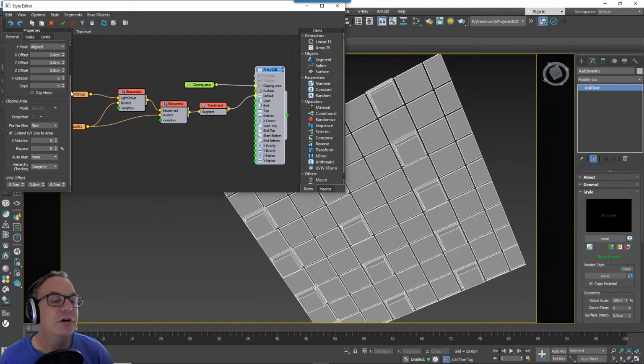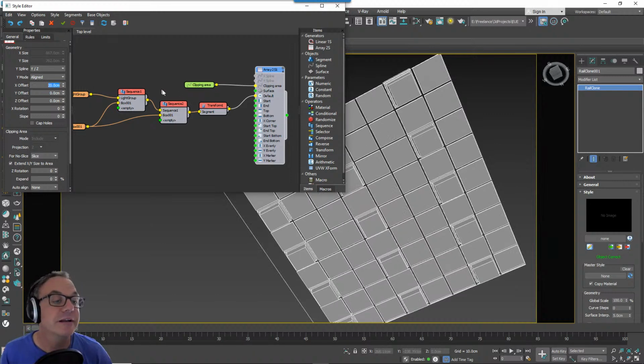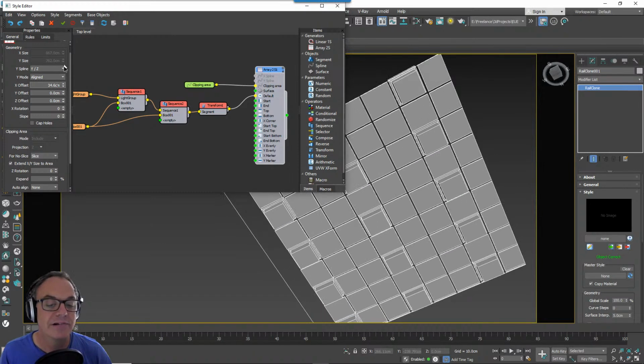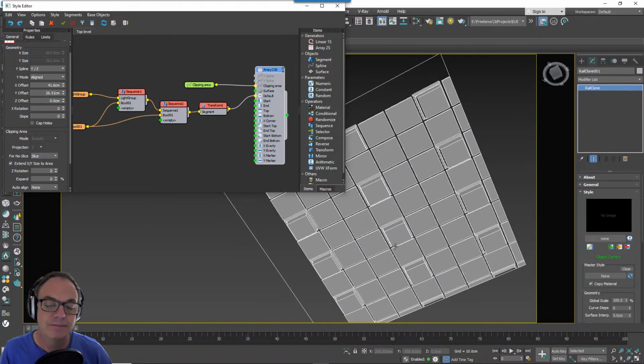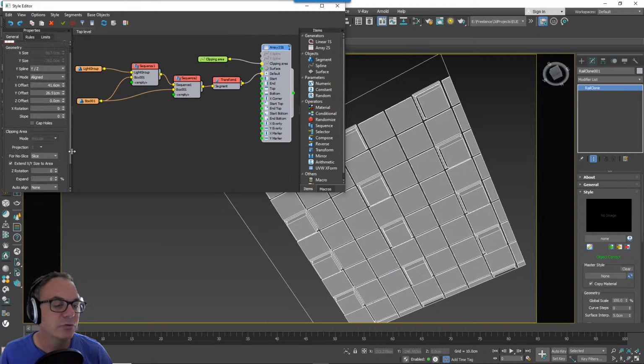If you go up a little bit here, there are X offset and Y offset modes. People have generally spotted these and they'll try to use them to slide the ceiling around. But as you can see, what happens is that gaps get created like this. I can slide it that way and that way, but it's not ideal because now we've got a gap where we can see into the ceiling void.